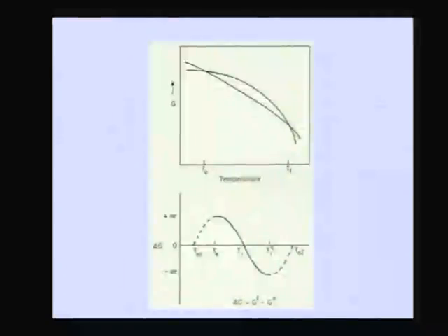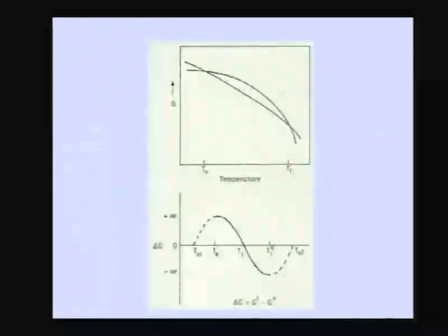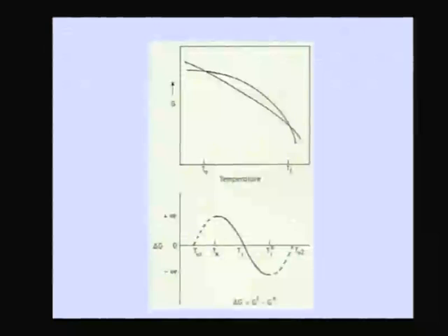and the free energy becomes more and more negative up to the TSI. At the TSI, you see that there is an entropy catastrophe coming into the picture, in that the entropy becomes equal for the parent phase and the product phase, and after that the free energy again decreases. If at all somebody can reach those temperatures, one can show that they decrease, and again you reach a temperature where the free energy again becomes 0.